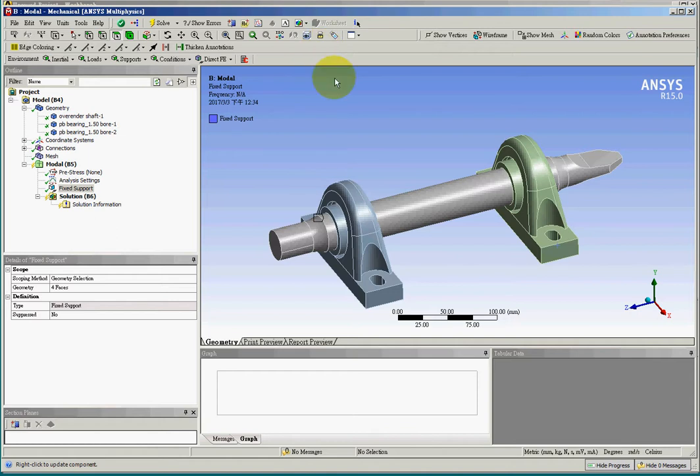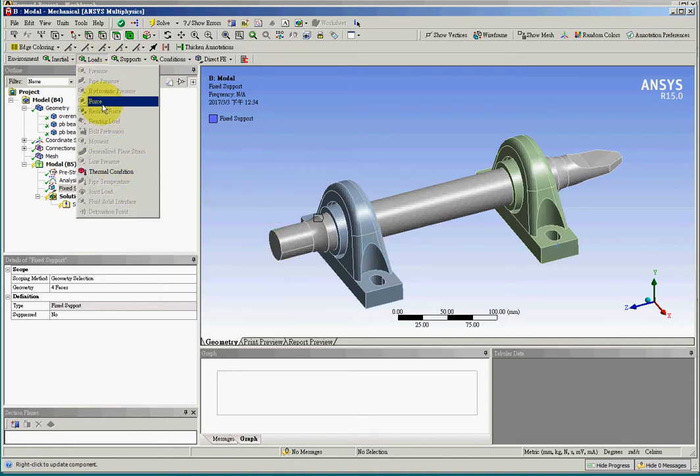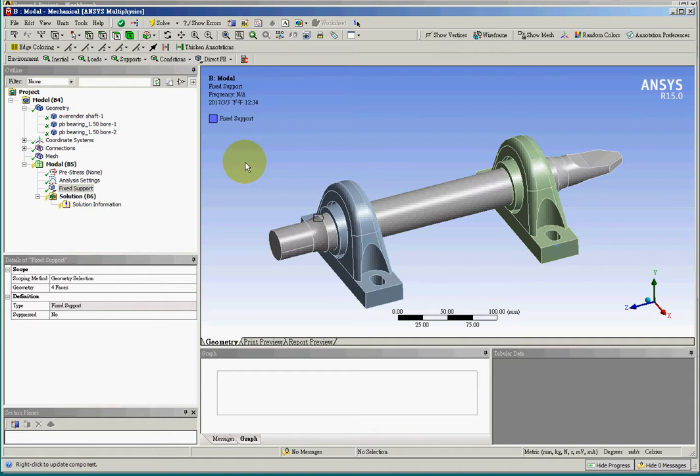And just as I said in SolidWorks Simulation, even if you want to place a load on the structure, in ANSYS it is blanked out. So ANSYS is quite a robust software. It prevents you from making mistakes. In SolidWorks, you can place a load on the structure, but the program ignores the external force. So the result is similar.